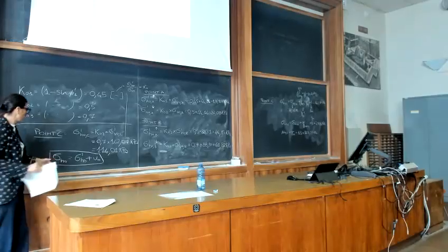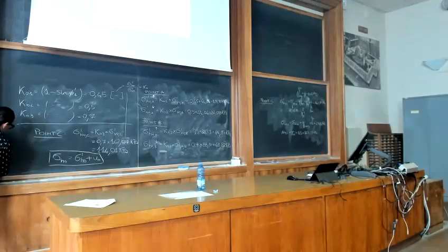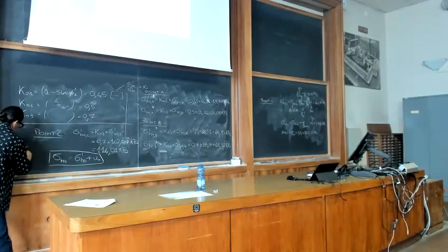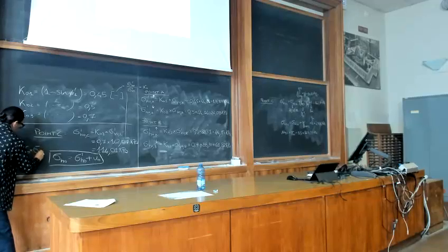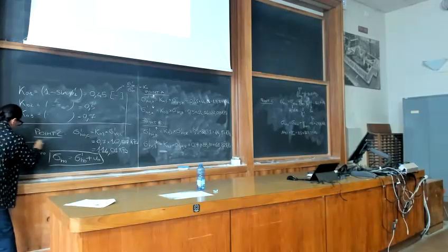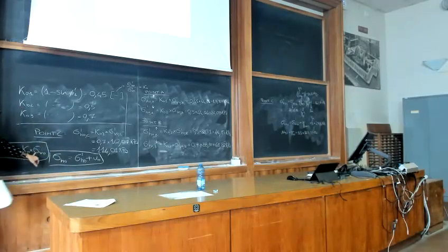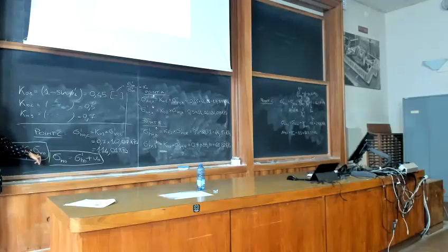Okay, so you cannot say that sigma H naught is equal to K naught multiplying sigma B naught, okay? Because inside here you have pore water pressure and the stress between grains. And if you do this, it means that you are applying the K naught of soil also to the fluid part of your material, okay?